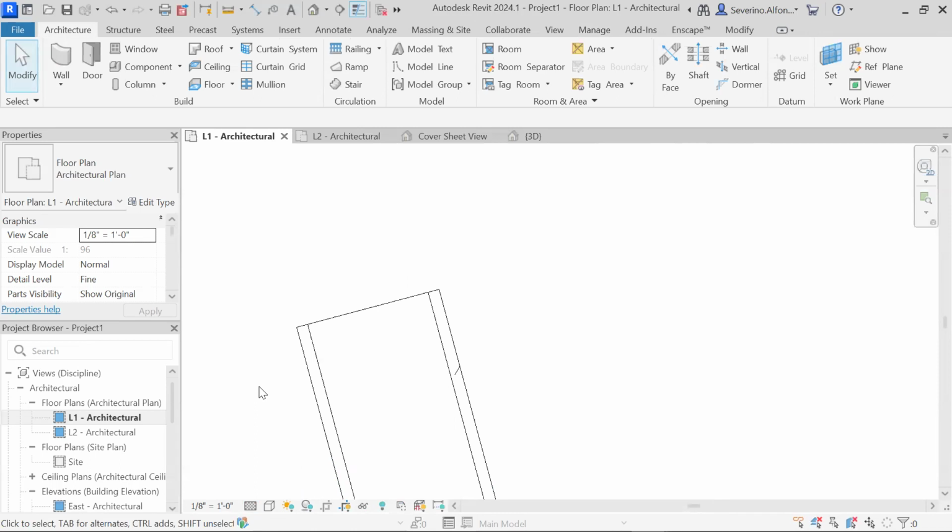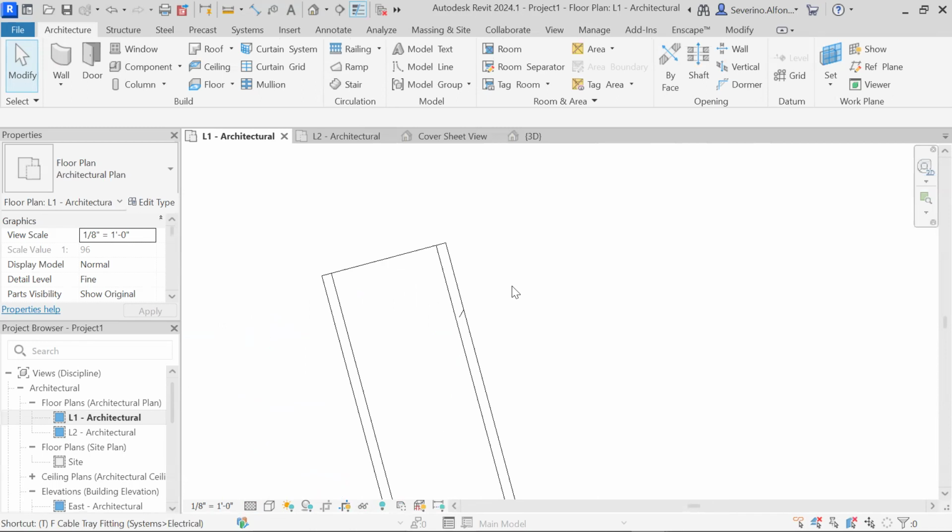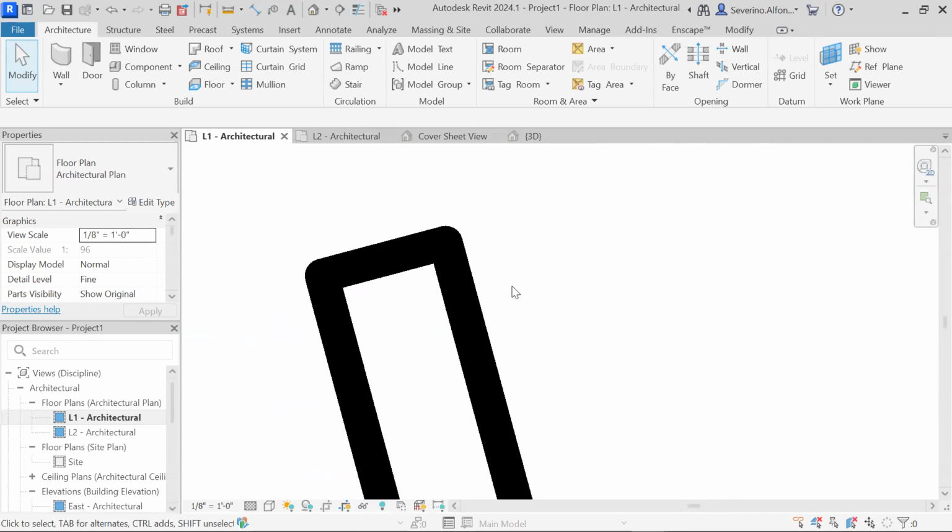By the way, you're seeing this very thin, like AutoCAD, because I clicked on TL, which is thin lines. In Revit, the shortcuts are very different from Rhino and AutoCAD in the sense that the way they work is only 2 letters. You don't need to click enter or anything. Thin lines, it doesn't. CO, copy, you don't have to press enter. It says that all F offset or whatever it is.